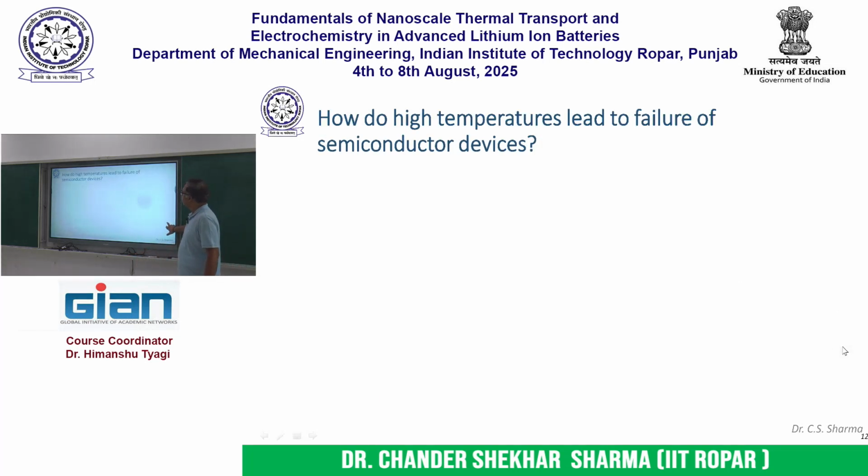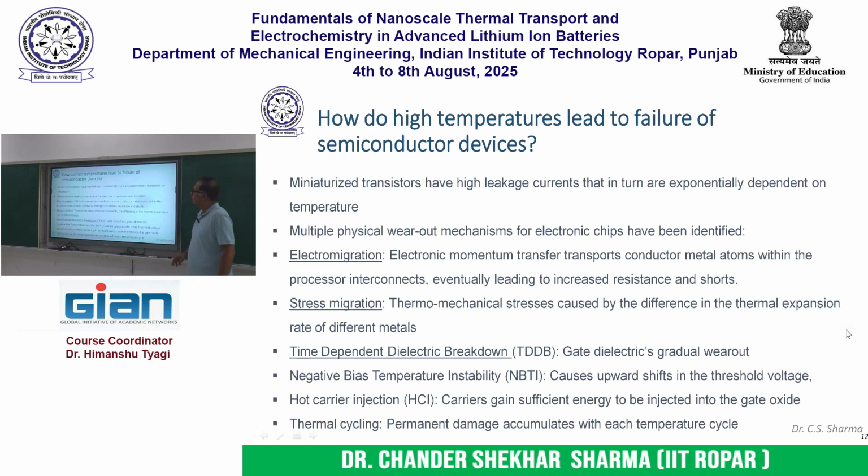In semiconductor devices, as the temperature rises, like a typical chemical reaction, as you would have seen in thermal management lectures in the course for batteries, new chemical reactions and physical mechanisms will trigger, okay. So for example, if the temperature of the device is high, it can lead to electromigration. So the interconnects between the microprocessors, there electrons can migrate and they can physically start displacing the atoms, and that can eventually lead to a loss of contact in an interconnect, and the processor can stop working.